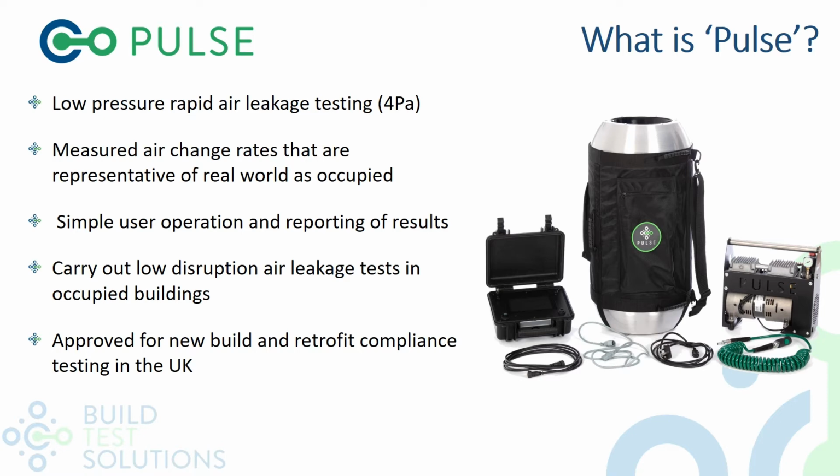And as I say, the main feature of pulse, the main innovation, is that it's measuring directly at those ambient conditions that are representative of real world as occupied conditions. By its nature, it's extremely simple to operate, and the results are easily obtained on the screen. Being low pressure, it's low disruption, so there are no service penetrations required through the envelope, and all the doorways are closed.